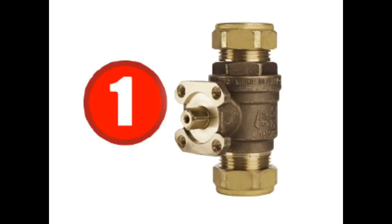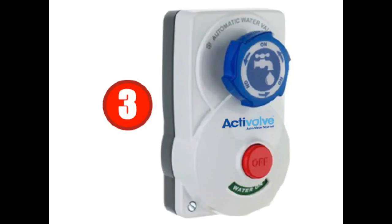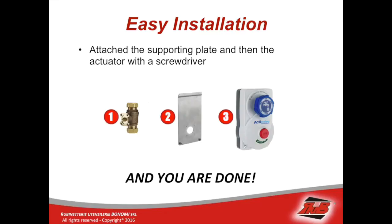Next, attach the actuator. Using a screwdriver, attach a metal plate to the valve using the screws provided. Then simply attach the actuator to the plate with screws that are also provided. Turn on the main water supply and check for any leaks. Activate the ActiValve by turning the blue knob counterclockwise until it stops. Then check the status window and it should read water on. Test the unit by pressing the red button to shut the water off. Then turn on the blue knob counterclockwise one more time and you're all set.